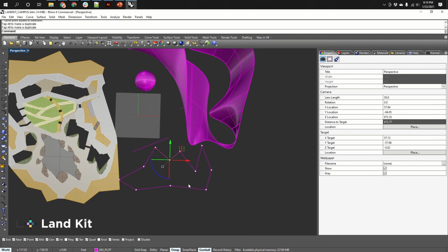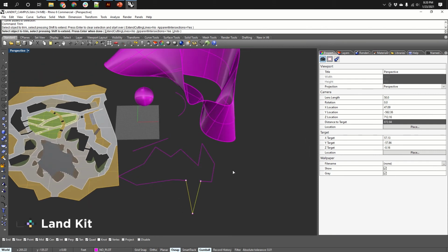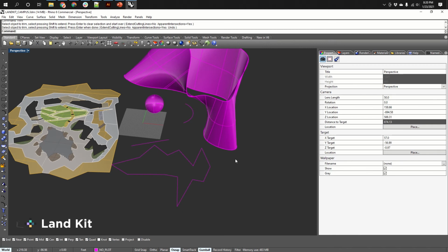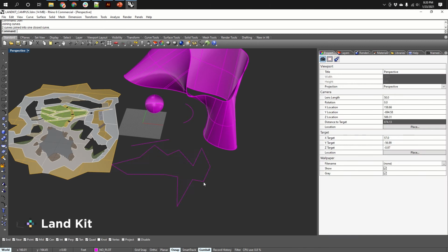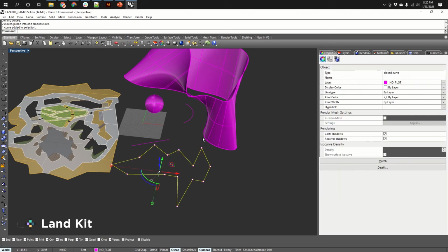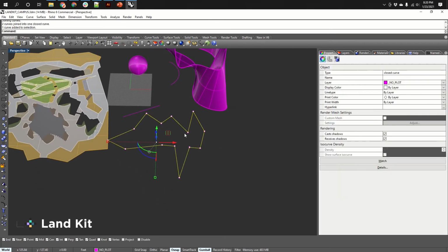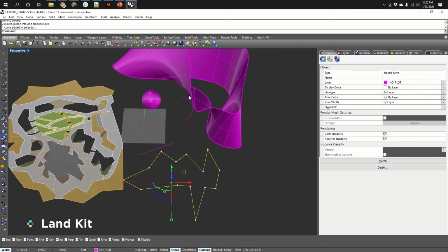You can also, if I type PL for polyline, and hit enter to be done with that command, select this and type trim and trim another curve. Right? So you can actually trim and manipulate curves that way. I can select both of these and type join, and they will join together into one single joined curve. You can actually have curves that have straight parts and curvy parts and arc-like parts. This is an arc that's going to have an actual radius.